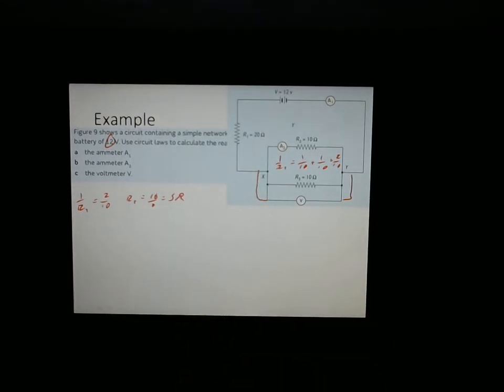And it is important to recognise if you have 2 resistors in parallel, doesn't matter what they originally are, your final result will always be less than either of them, because what we're basically saying here is that it's easier to go through 2 things in parallel than to go through just one thing on its own. Okay? More electricity will always go through.